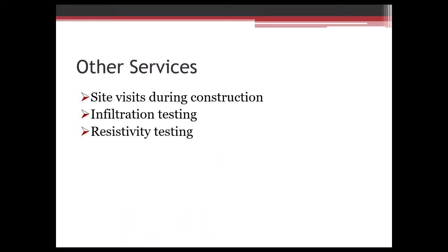Other things that geotechnical engineers can do during the project is, one thing I really like to do personally is site visits during construction. It's really nice when you go out after you did a slew of borings on a site and find out that the conditions that are actually there in the foundation excavations are what you expected. And I will say that that's not always the case. There are some times where things come up during excavation, and that's definitely where you should involve the geotechnical engineer for site visits so that you can determine the best way to handle those as quickly as possible so that we don't cause delays with construction.